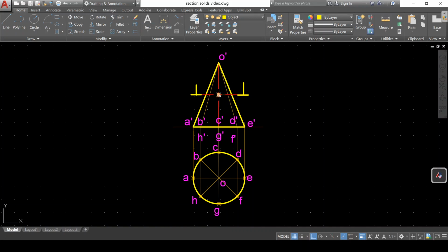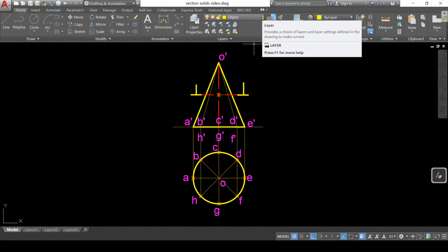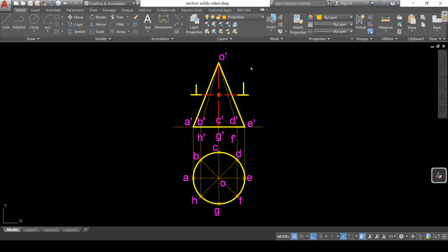Basically these points are easier except this point, which we have to transfer using the process we used for the pyramid. So let us see this first. We have to transfer the point P3. Actually two points would be there, one on OC and another on OG. So P3 and P7 are the points. How do we transfer them? The process is the same. We first transfer them horizontally.